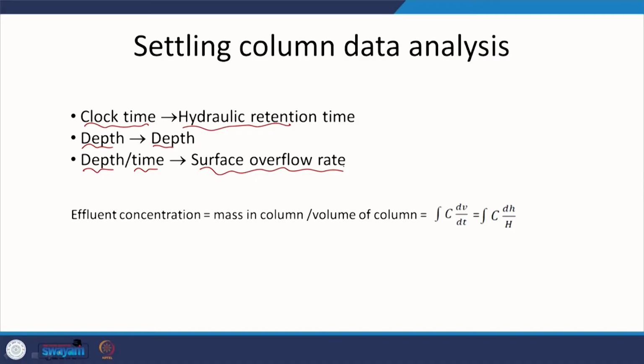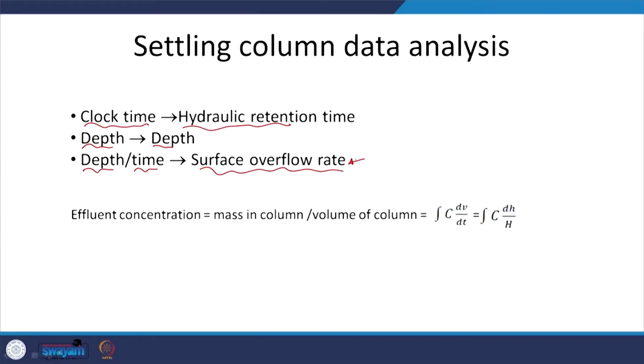Surface overflow rate we discussed earlier, and I plan to discuss this after a few slides. In general, surface overflow rate will give me an idea about that critical velocity, beyond which, depending upon the type of tank, whether it's upflow or horizontal, either no particles will be removed or only a fraction of the particles will be removed. We will come back to this.